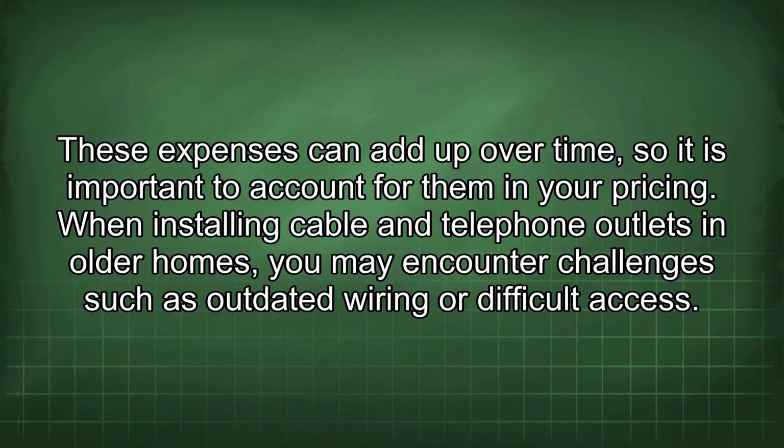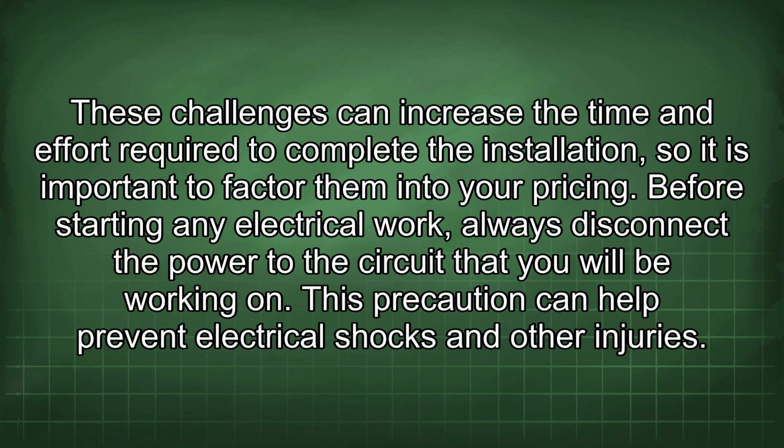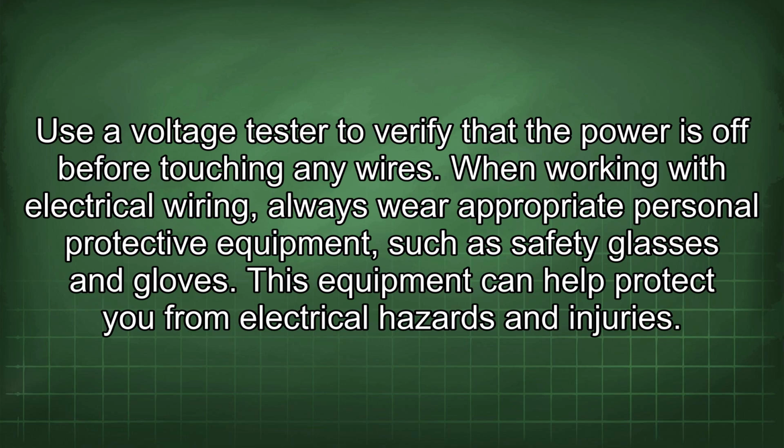When installing cable and telephone outlets in older homes, you may encounter challenges such as outdated wiring or difficult access. These challenges can increase the time and effort required to complete the installation, so it is important to factor them into your pricing. Before starting any electrical work, always disconnect the power to the circuit that you will be working on. This precaution can help prevent electrical shocks and other injuries. Use a voltage tester to verify that the power is off before touching any wires.